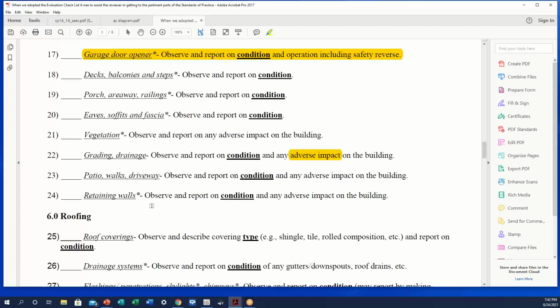5 feet. Yeah, anything over 4 feet is a retaining wall, everybody. You just said 5, you said 4. Yeah, I know. I said 5 because that's the limit that you can go without additional engineering. Yeah, right. So what he's saying is a patio wall is 5 feet, but a retaining wall in the code, again, I'm throwing something out here, anything over 4 feet requires engineering.